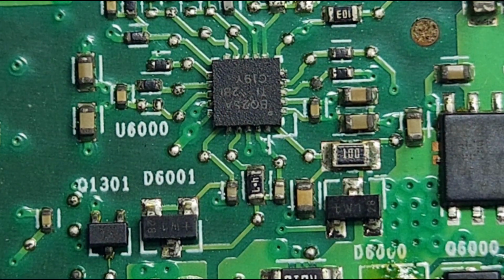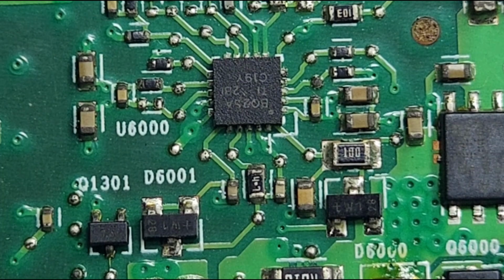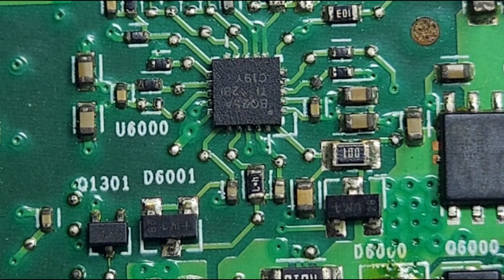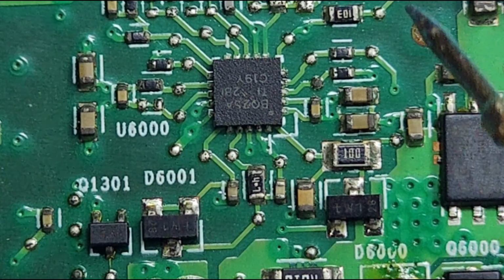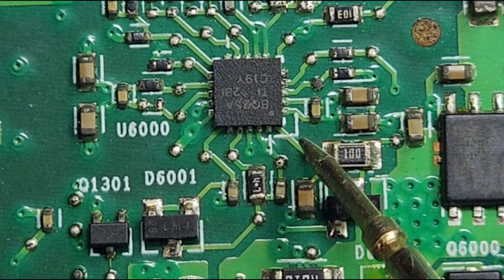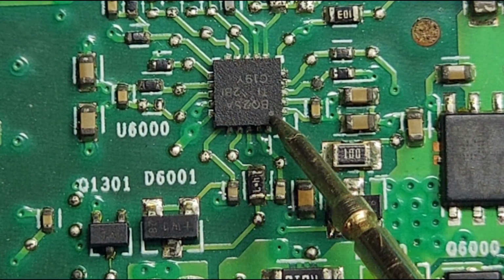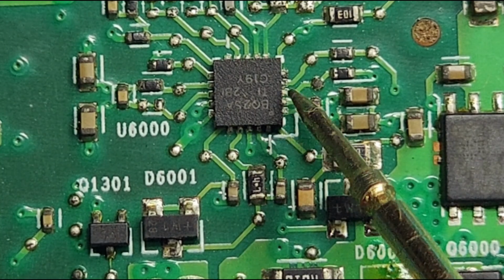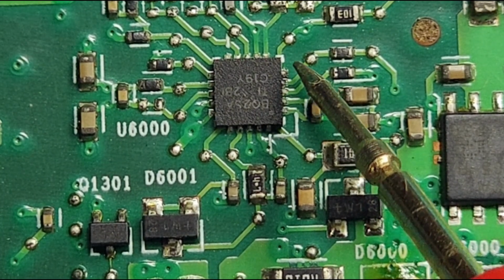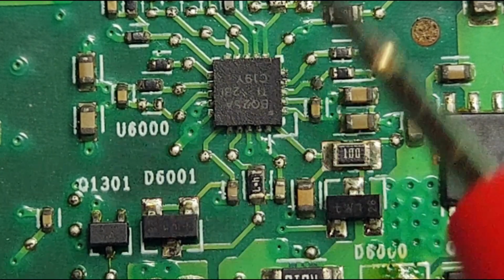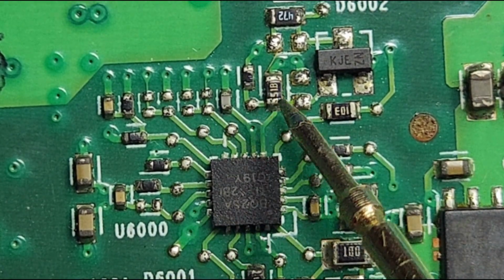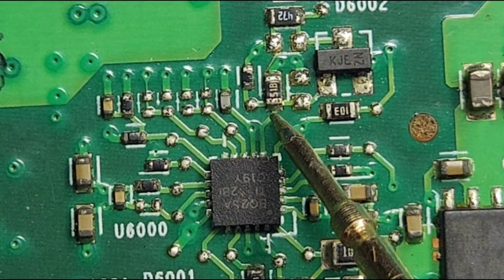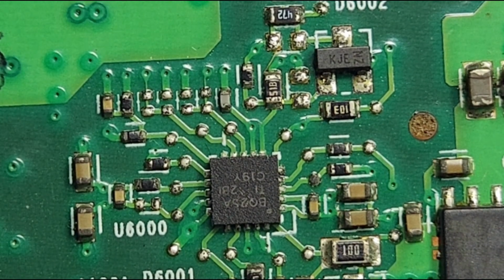Okay, now let me connect the adapter. The adapter is connected. So we need to check on pin number 6 whether we have 2.4 to 3.15 volt. So pin number 1 is on this side. Here we have the dot. So pin number 1, 2, 3, 4, 5, 6 is on this side here, straight away from this resistor here. Okay, let me check the voltage.